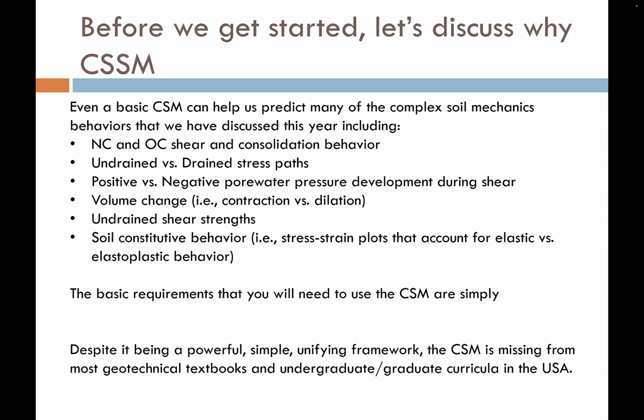Those behaviors include, but are not limited to, by the way, normally consolidated and over-consolidated shear and consolidation behavior, undrained versus drained stress paths in shear loading, positive and negative pore water pressure development during shear, volume change during shear, either contraction or dilation, undrained shear strength prediction, and soil constitutive behavior.